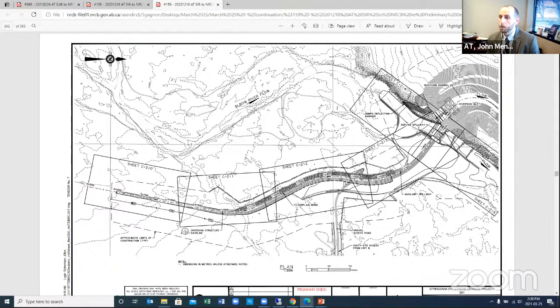We have the ability to lower those gates under their own weight without any power, using manual brakes on the gates. But in all of those scenarios, if water still enters the channel and the dam is up to the emergency spillway elevation, at that point water would go over that emergency spillway and then be redirected back to the Elbow River again. But as I said, that would be in an extraordinarily large flood event and would constitute a malfunction or failure of the project to operate as proposed and intended.